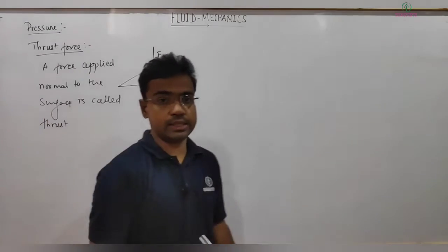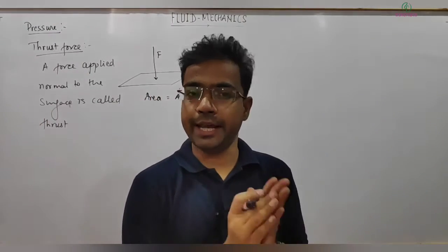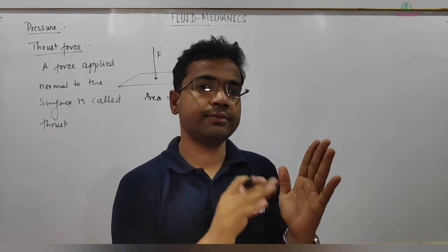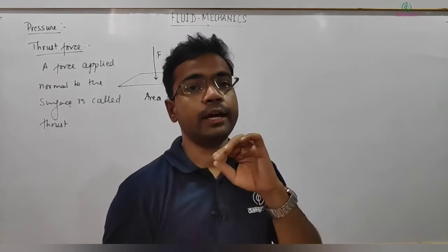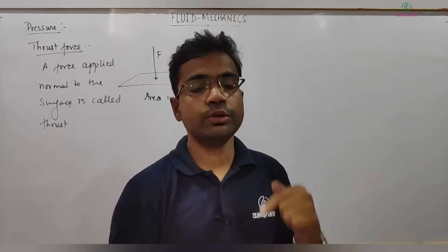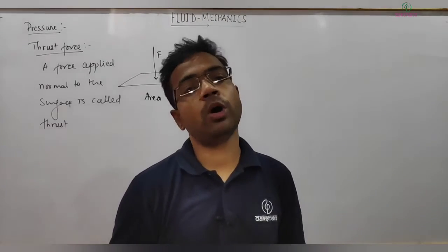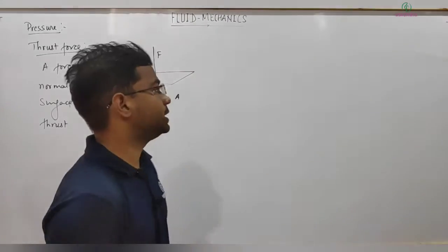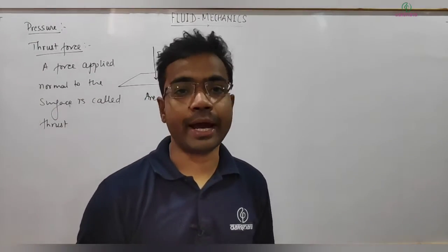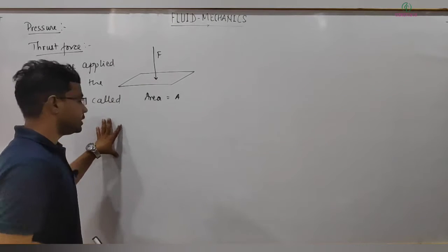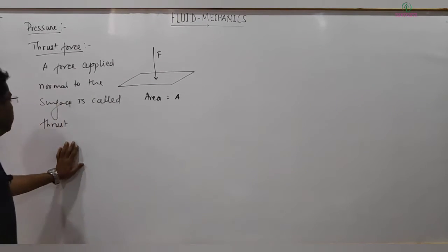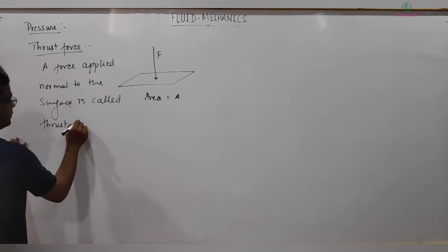Actually, if you consider any surface like a fluid, whatever the surface it is in contact with, the fluid always applies a force perpendicular or normal to every surface. So the force applied by the fluid will always be a thrust force. It never applies a force in the tangential direction or at some angle. It always applies force normal to the surface. So this is always called thrust force.